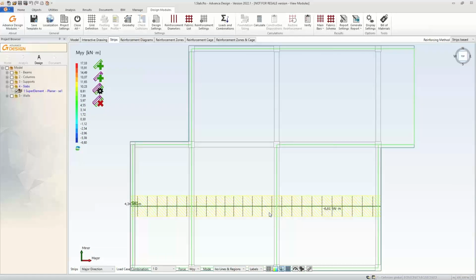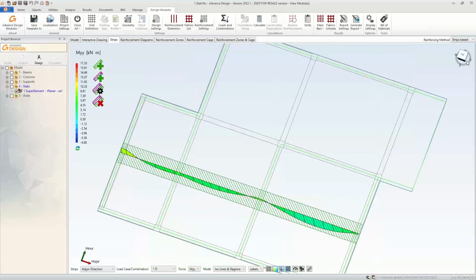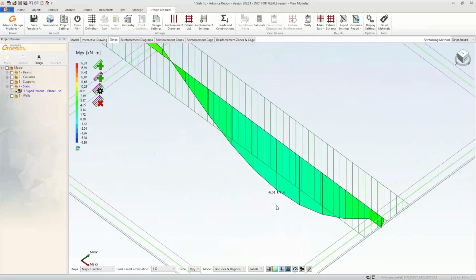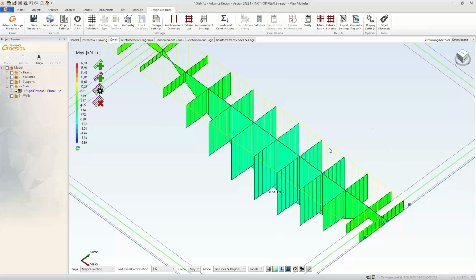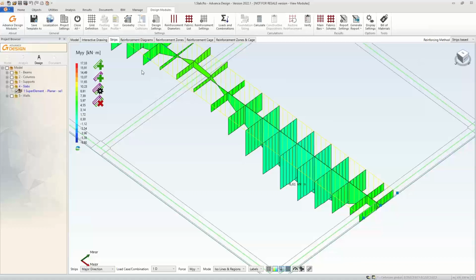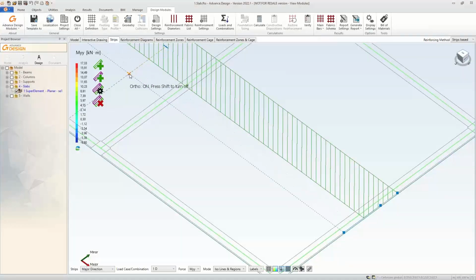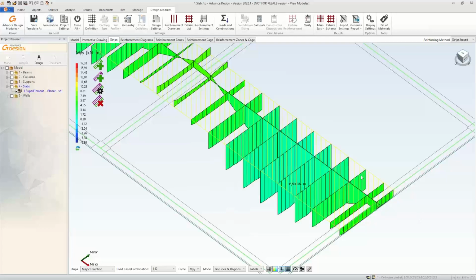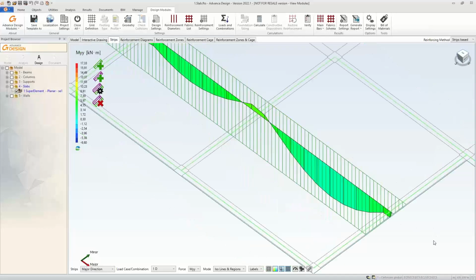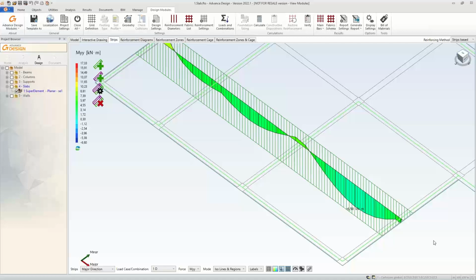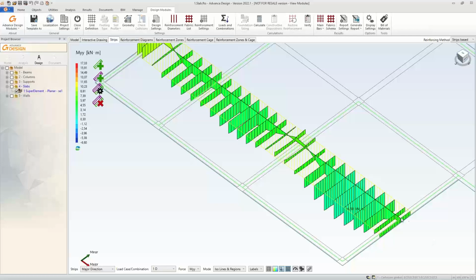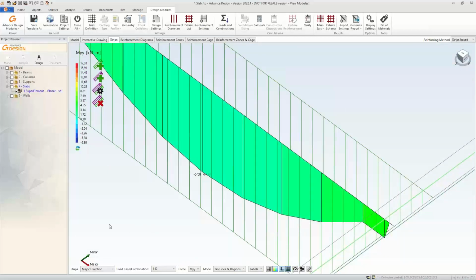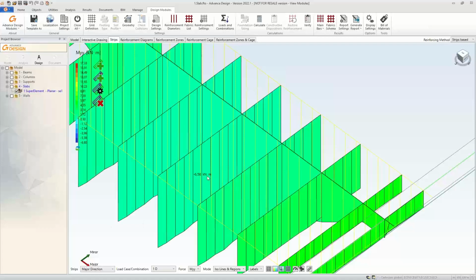If the strip width is different, maybe you will see the values. The maximum value is 6.6. Probably when I change the width, we see that the value changes a little bit, because values are integrated along that strip, and what we see on those 2D diagrams are values, of course, per meter. It's not the maximum value. It's integrated, and we see, I don't know if the unit is visible, kilonewton meter per meter.